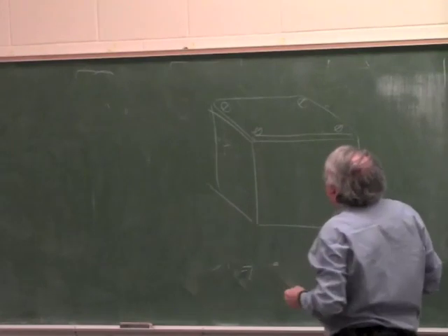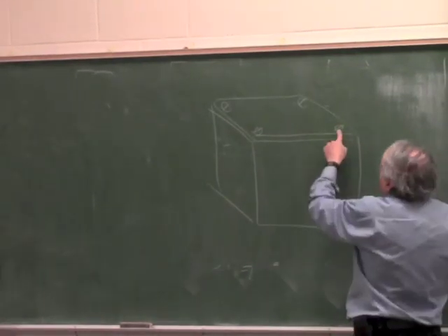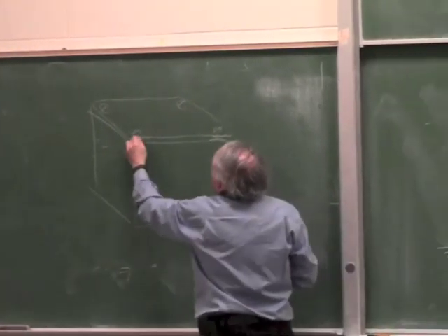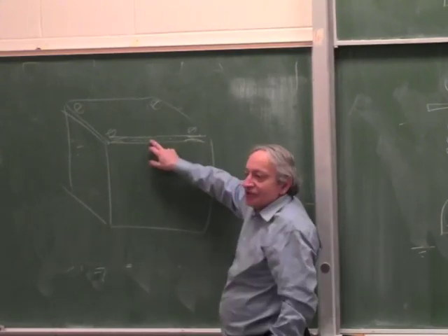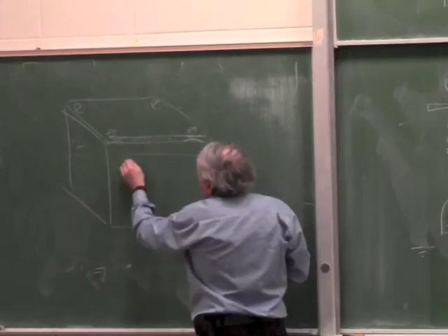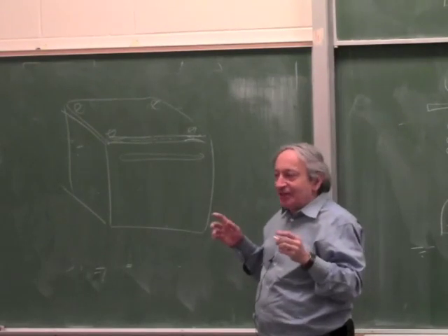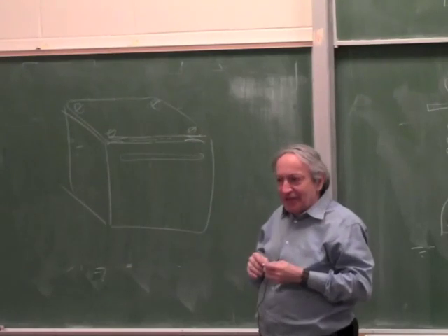But if you're dealing with very high frequency, this may not be sufficient, because the 4 screws will guarantee electrical contact where the screws are, but there may be no electrical contact here, so it will be the same as having a slot. And if that slot is big, it can act as an antenna. An electromagnetic field can come out.